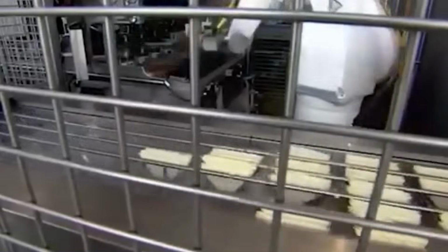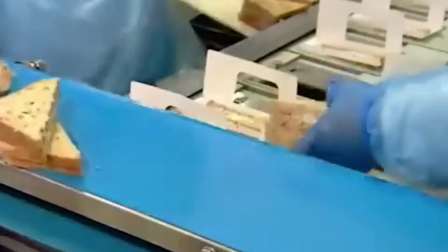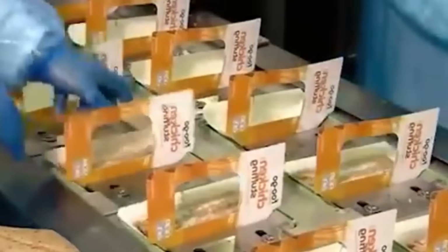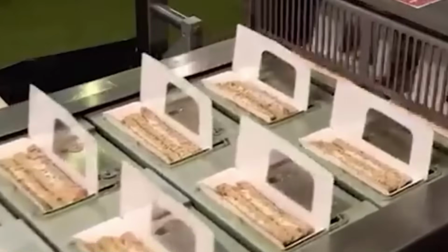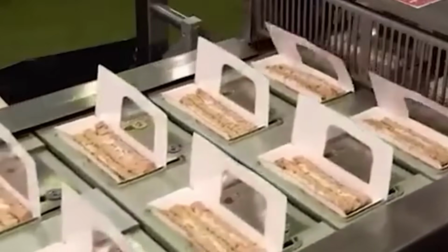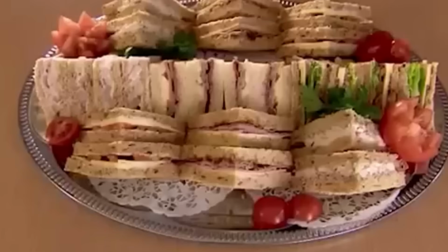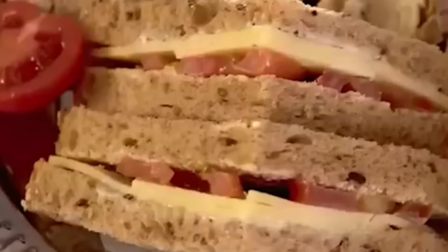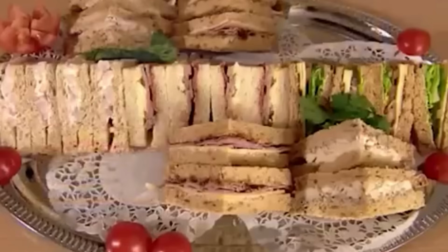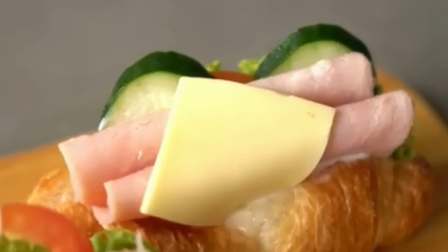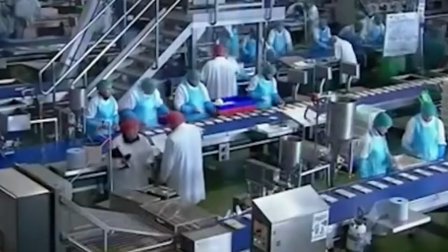The accepted sandwiches pass into the packaging zone, where the method of wrapping depends on the product's end use. For flow-wrapped sandwiches, the product enters a film feed tunnel where printed plastic film is drawn over and around the sandwich by guide belts, sealed along the back and ends by heated jaws that press and crimp the film closed in less than a second. A date coder prints production information onto the film surface just before the end seal.